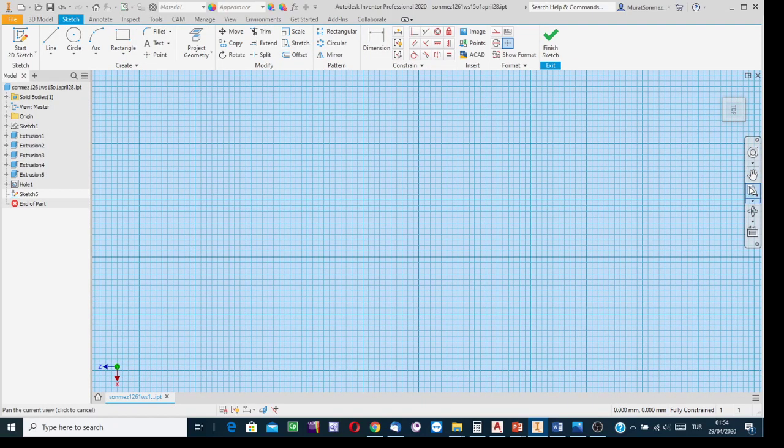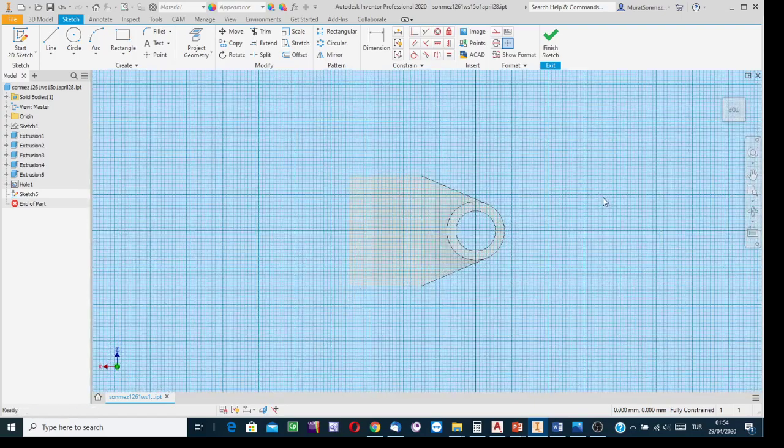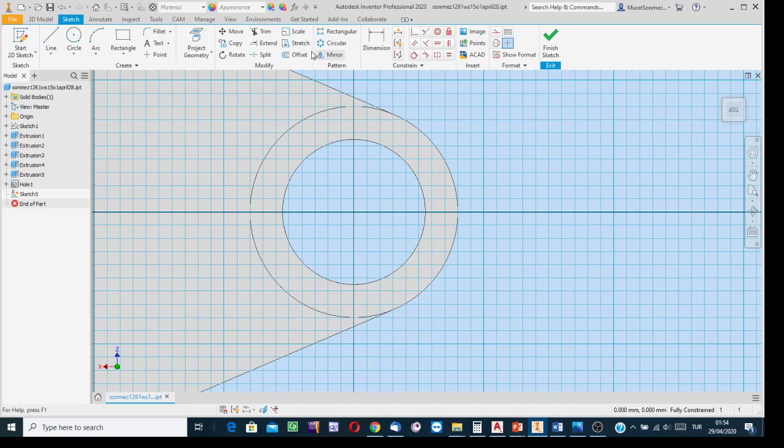And then, in sketch mode, create a rectangle with such further extensions, and then upload the dimensional constraints. Doing this, I need to use the projection of the edge of the hole, the project geometry process: indicate the edge and have it as projection.